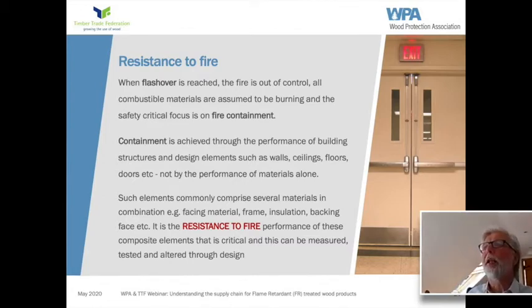Now, the reaction to fire and fire resistance classifications are really what I was referring to at the very beginning when I said people get in a muddle about specifications. We've had a number of contractors on to our helpline saying, I've got this specification, it doesn't make sense. And when you look at it, it's because the specifier has completely mixed up the concepts of resistance to fire and reaction to fire. They are completely different things.